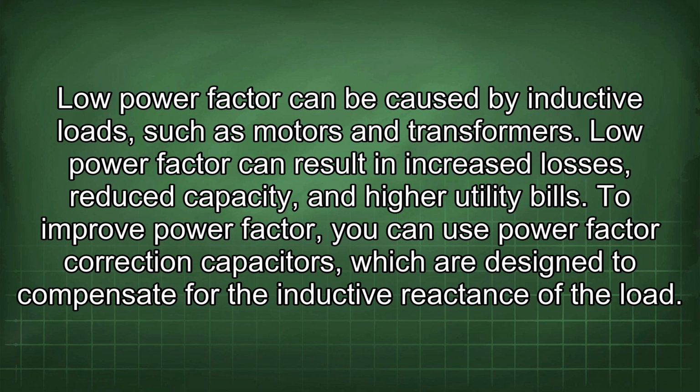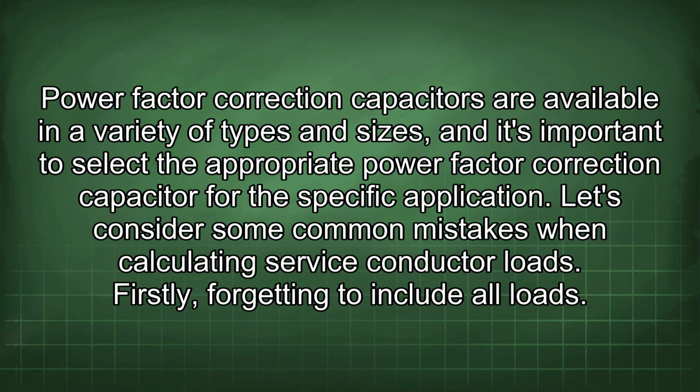To improve power factor, you can use power factor correction capacitors, which are designed to compensate for the inductive reactance of the load. Power factor correction capacitors are available in a variety of types and sizes, and it's important to select the appropriate power factor correction capacitor for the specific application.